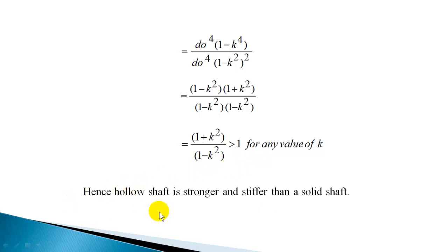Hence we have proved that a hollow shaft is stronger and stiffer than a solid shaft. So it also proves that the torsional rigidity of the hollow shaft is greater than that of a solid shaft.